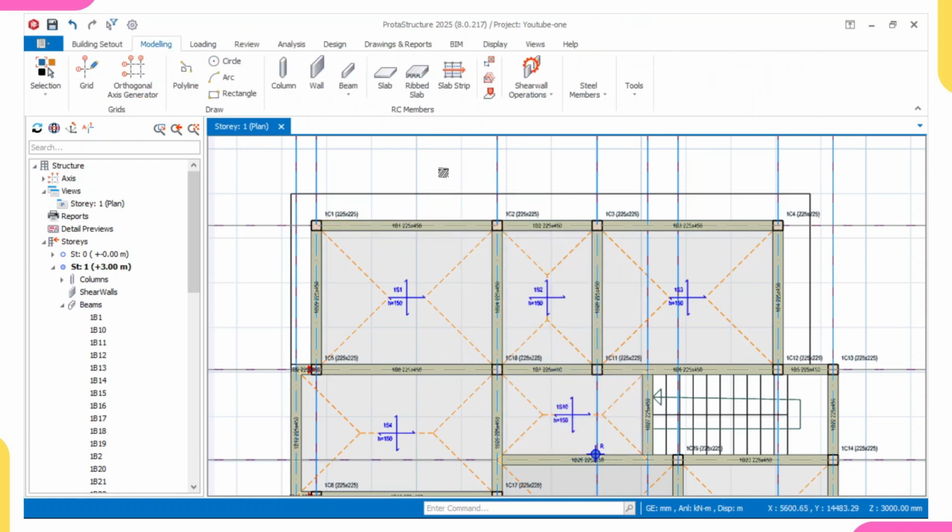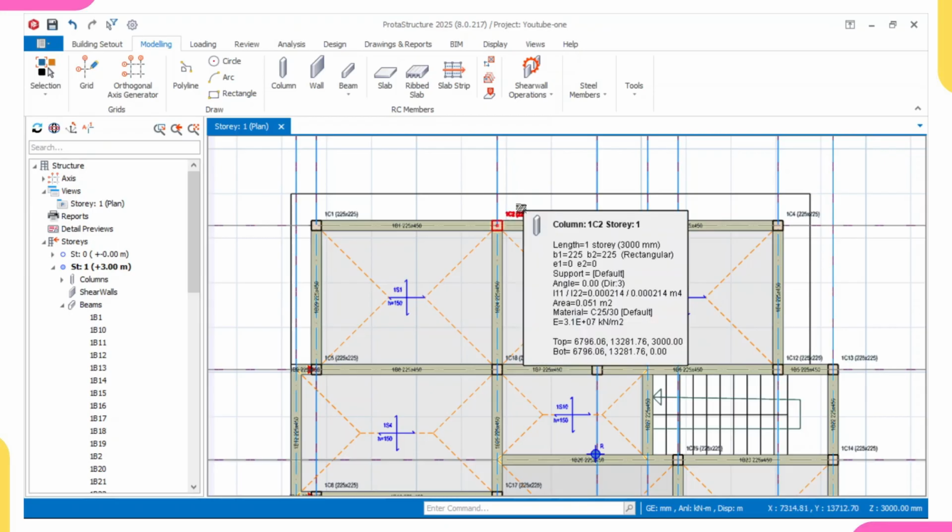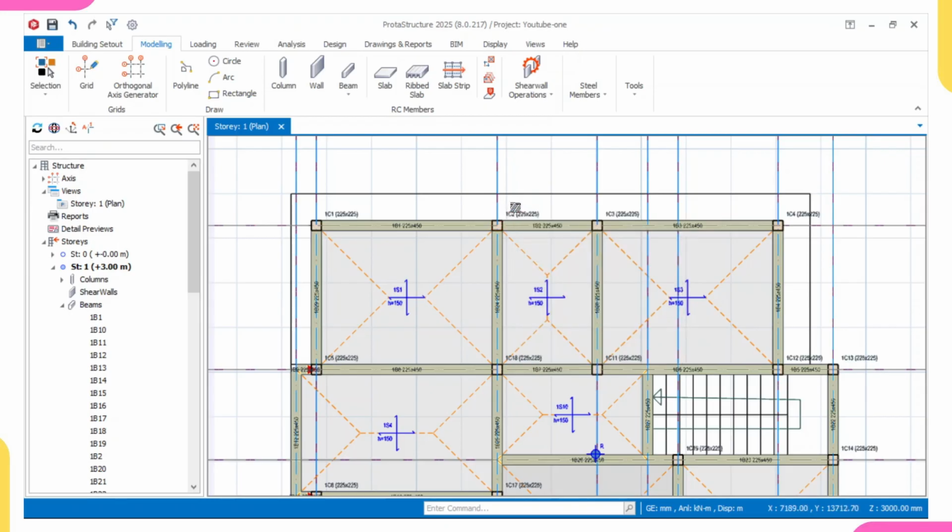We'll be having a moment going in this direction, and this side will be having a moment going in this direction. So one will be positive and the other one will be negative. Something like we'll be having positive 30 kilonewton here, and this side we're having negative 30 kilonewton. If you sum both of them, since one is positive and the other one is negative, you'll be having 0. Yes, because the summation of moment at any point is equal to 0.